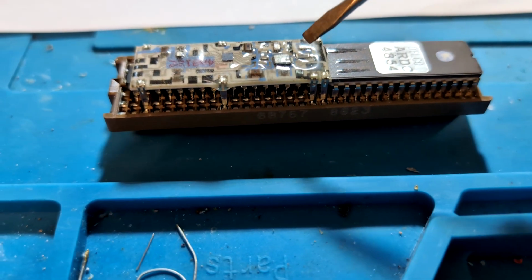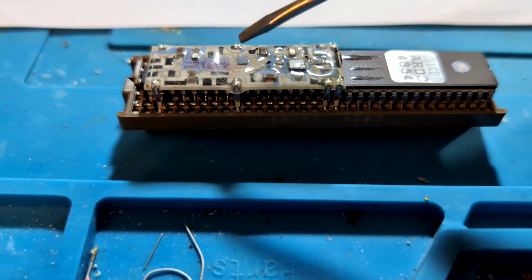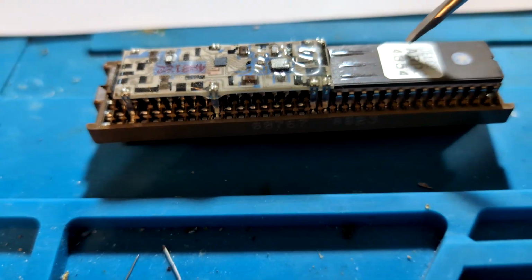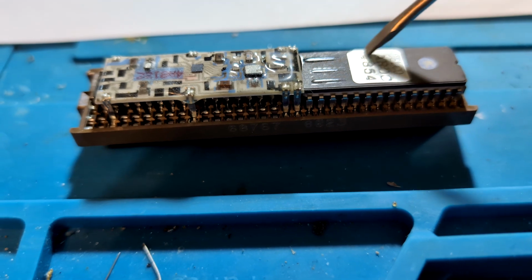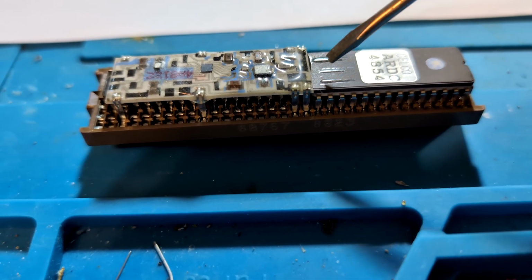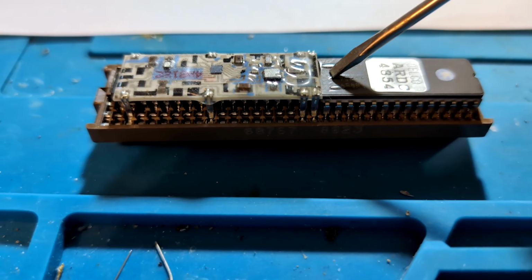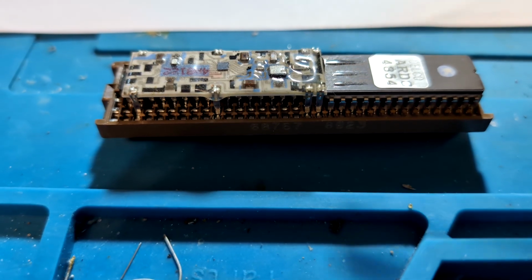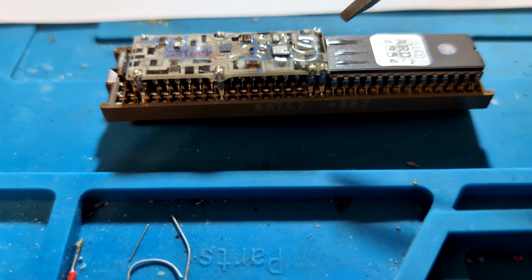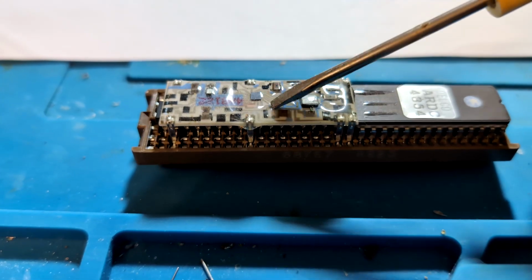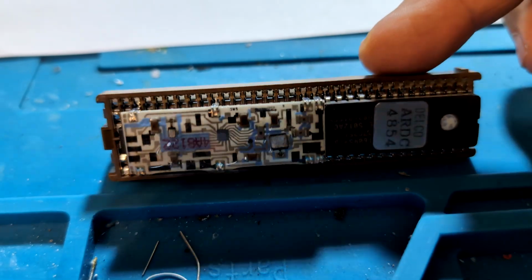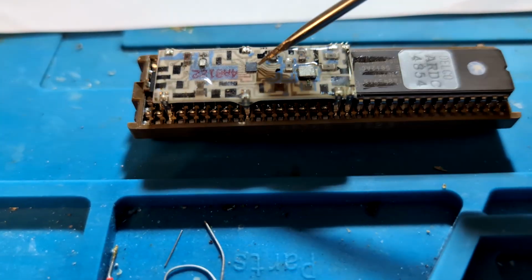You still will not have the proper knock sensor circuit here. I just want to stress that. Even if you do put this jumper in, this Memcal, assuming you change this program to the proper TPI program, will now effectively run your car perfectly fine as a V8 TPI car in your 1227730, but this knock filter is not tuned for a V8 because this was from a V6 car. So this knock filter is not correct.